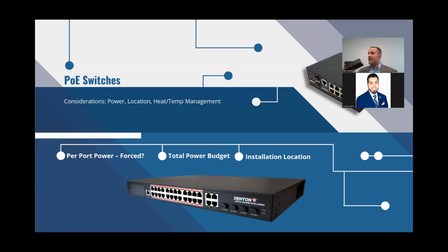Now, there's also another element that you need to know about. There are a lot of manufacturers that have a forced 90-watt PoE setting, and that's how they handle PoE lighting. I'll give you some really good manufacturers. Transition Networks, who have transitioned to a new name, I can't remember right off the top of my head. Lantronix, that's it, Lantronix. Lantronix switches, you do need to learn how to set the power setting to forced 90-watt PoE for certain PoE lighting manufacturers. Cisco is very good. We found the Cisco switches power up very well, but your performance may vary.